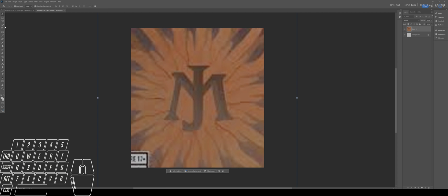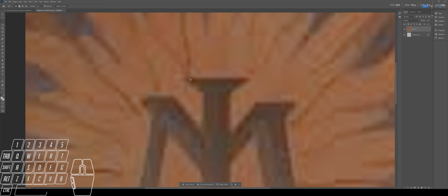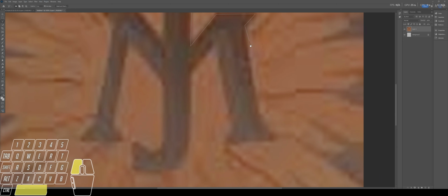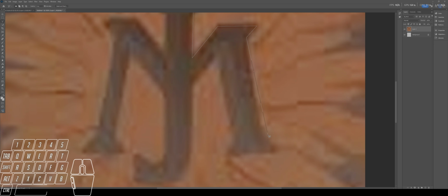So what I'm going to do now is I'm actually just going to go to my selection tools, and up here we can find one for our lasso. By default, it just looks like a lasso up here. But if I right click on it, I can actually go to magnetic lasso or polygonal lasso. For this, we're going to use our polygonal lasso actually. And what this is going to do is just allow me to draw some points together and trace the shape of this point. I can still use my normal navigation, so I'm just holding space and dragging my left mouse button to move my viewport.